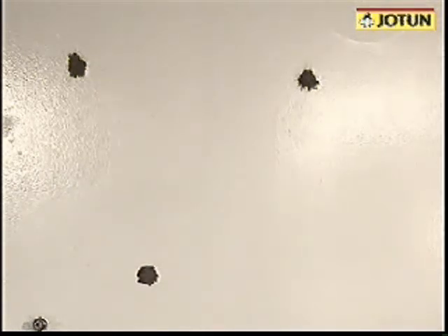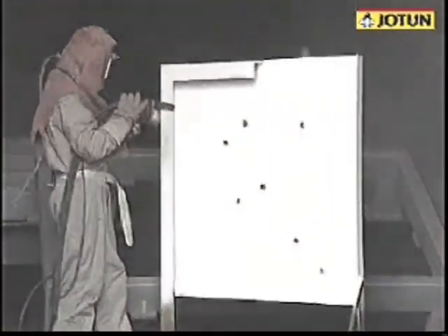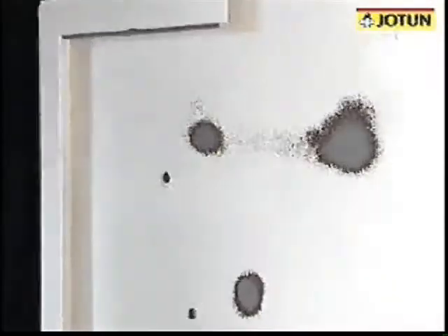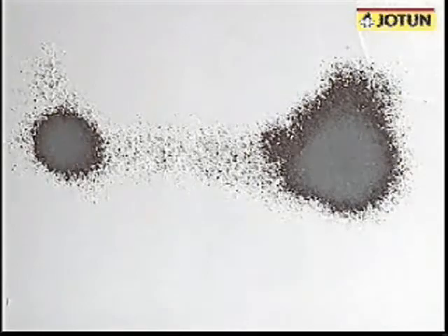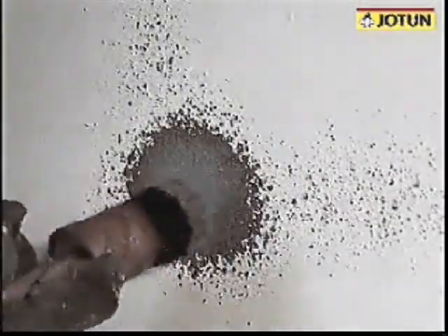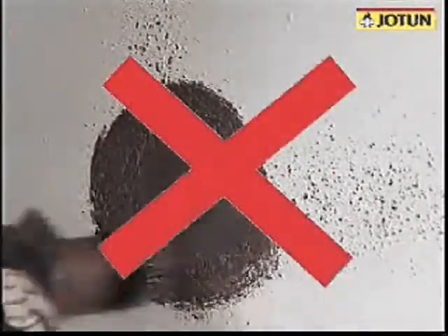A painted surface may suffer from damage in only a small part of the total area. The steel inside the damaged area will be corroded and the paint edges will be loose and sharp. Spot blasting is often used to remove the rust prior to maintenance painting. Unfortunately, the intact paint around the damaged area may suffer impact damage. Never paint on such areas without first grinding or feathering the edges of the damaged paint.